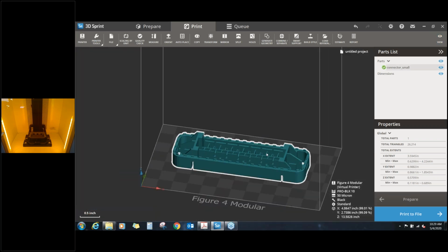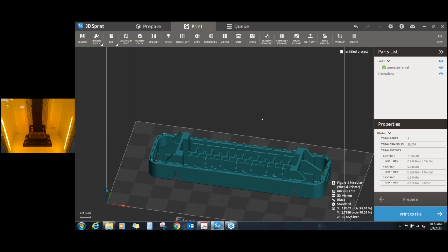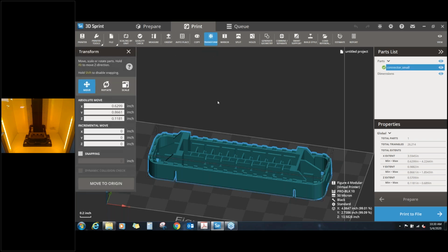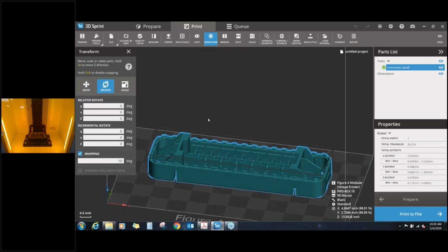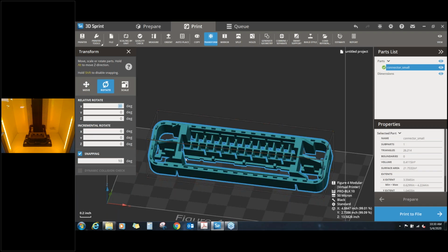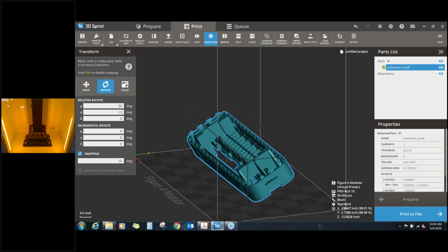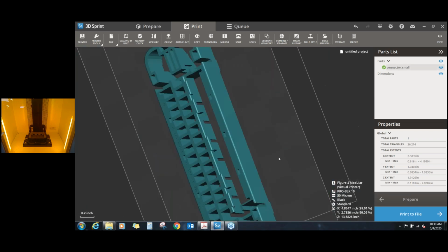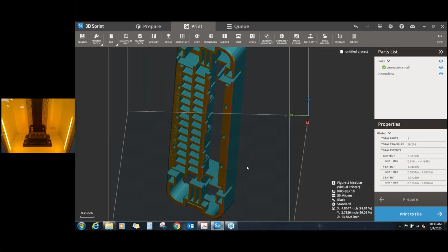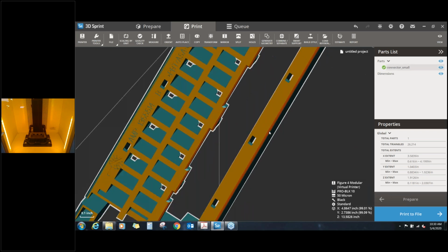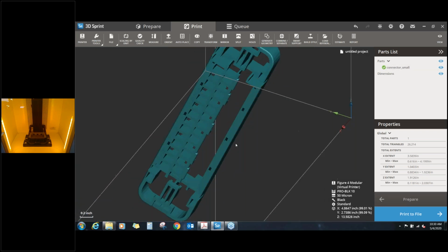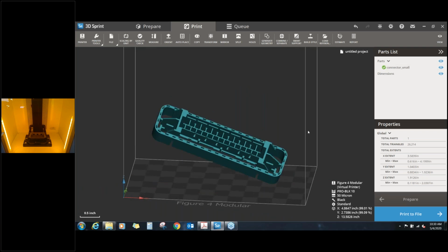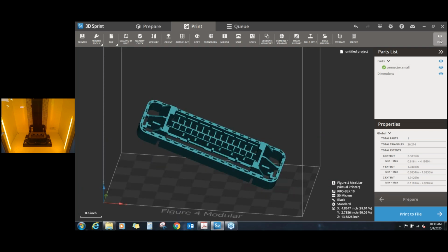So what we like to do on a large majority of parts, medium to large size that can fit in this, is we'll come over and we'll actually orient our part on a compound angle. So I like to play around with sometimes 30 degrees in the X and then maybe 20 degrees in the Y direction. That's just a starting point. And what you'll notice is underneath, areas before that were dark red that required supports, well, now they're switching more towards orange and yellow. So they're still necessary, but not quite as critical.